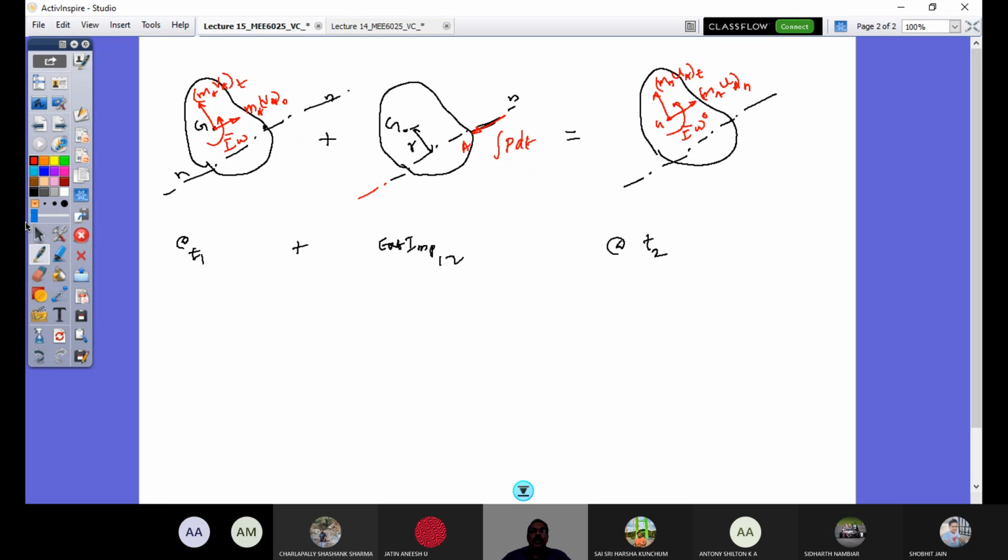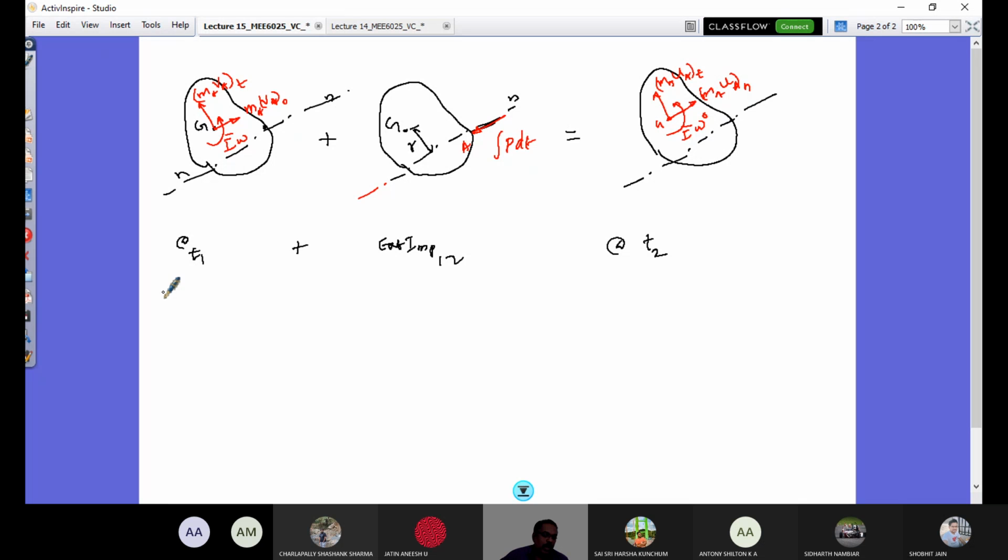So if this is so, now how do you apply your angular impulse and momentum equation? So here it's very clear. This V is what is just before impact. U is the velocity, common velocity of the contact surface, but I consider only one vehicle, so velocity at the maximum deformation state. And omega is the angular velocity just before collision. Omega naught is the angular velocity at the maximum deformation point.